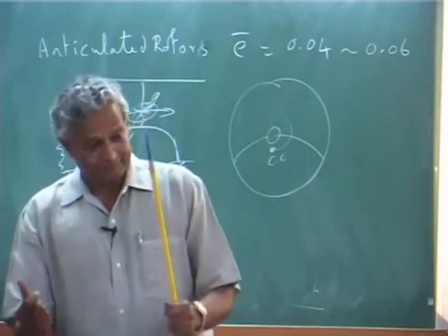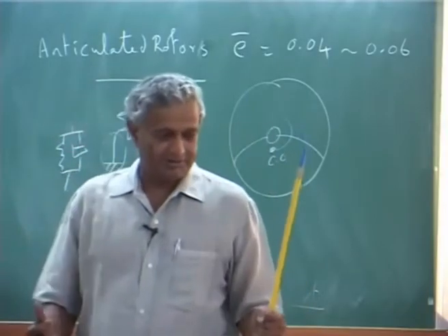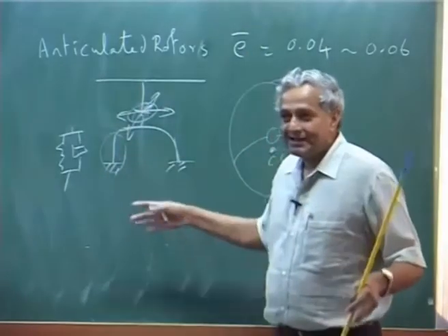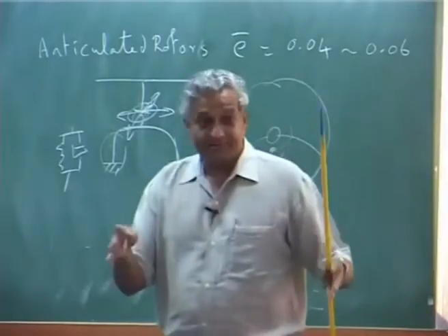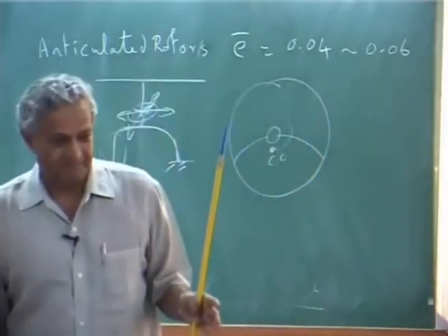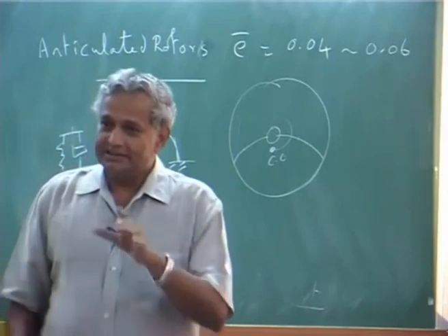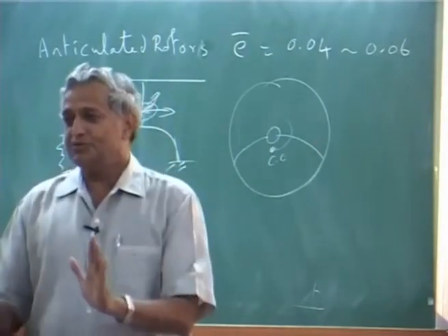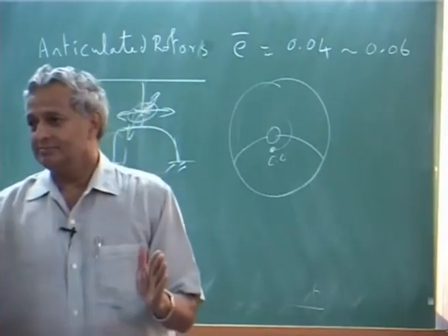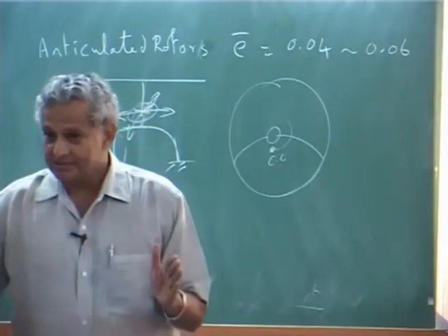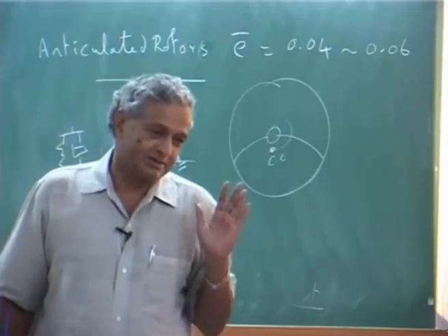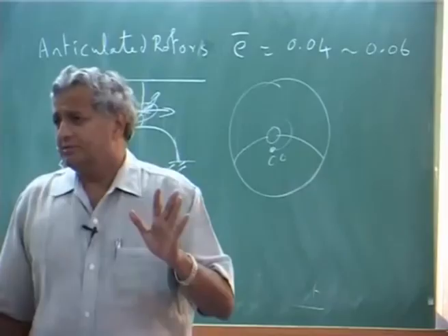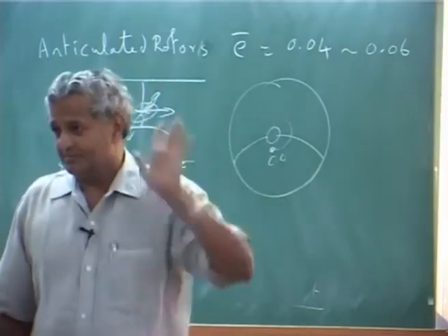The wheel type, yes, they had initially some problems, and then they had to put a damper, increase the damping here, tire pressure, everything matches. It should be very, very critical. So, the analysis you do, finally make sure that during your operational range you do not get into ground resonance problem, and one of the ways to avoid it is to put dampers.